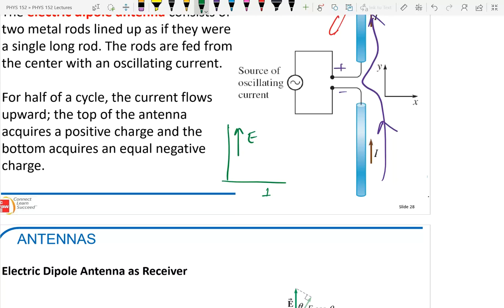And so by having the natural frequency of your circuit match the natural frequency of the broadcaster, you can actually amplify that frequency. So it's possible to make a little radio that is just very simply a long wire for your antenna, and then have a little resonating circuit.